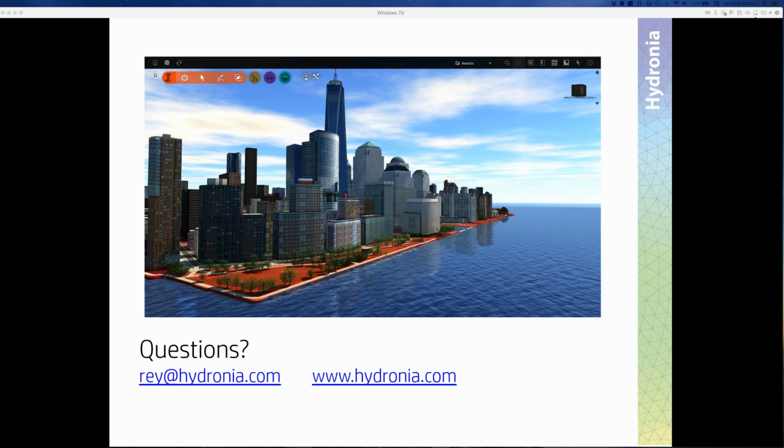The user provides the water surface elevation versus time, and the model determines the discharge either out or in. So if you have an estuary condition, you select your tidal record or your storm surge, and the model will calculate the inflow and outflow.